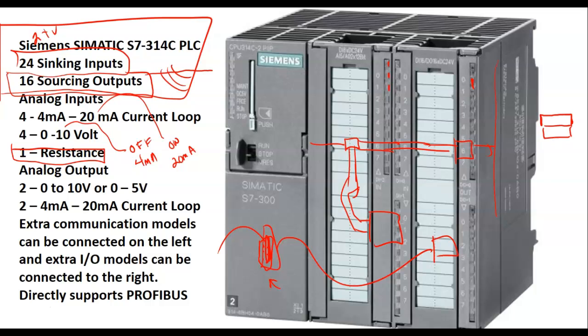If the 24 volts is not getting to the relay, then there's a broken wire between the PLC and the relay. If the 24 volts is getting to the coil of the relay, then that would mean what? That the relay is bad. And relays go bad, guys. They got a bunch of coils of wire in there, and the wiring is so thin on the relays because it's using what they call magnet wire. It doesn't take much chafing to cause those things to go out.